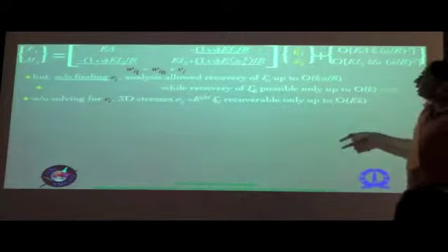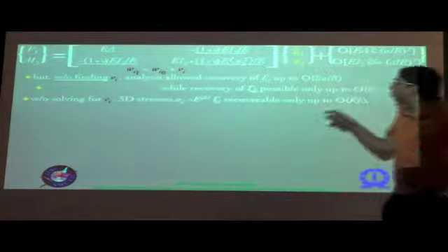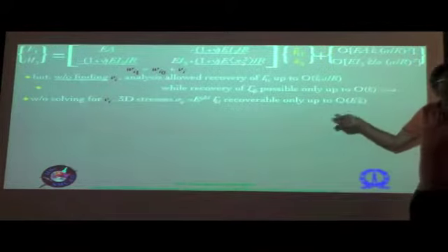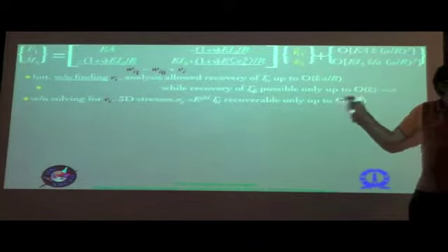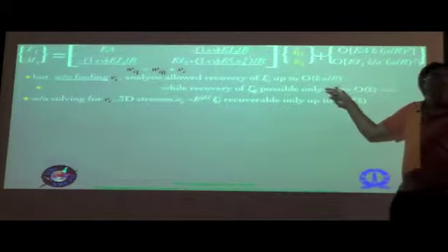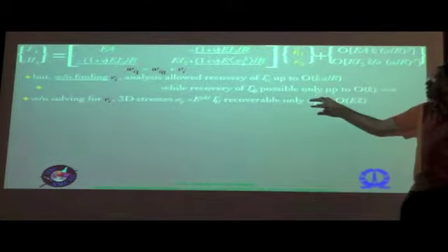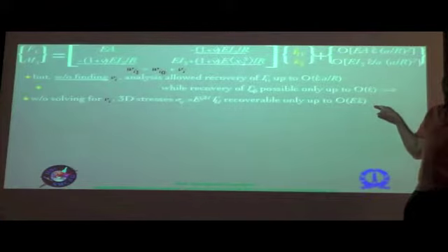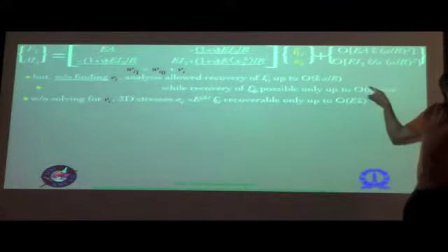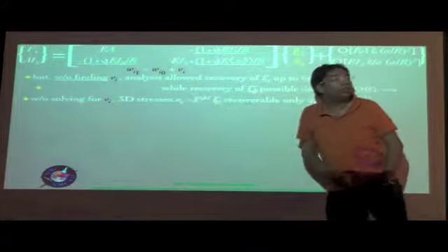Therefore, in the stresses also, you would have the recovery only up to E times epsilon hat. There would be some spurious terms coming because of this, but you cannot say that the stress is accurate up to the order E epsilon hat into A by R, because some of those were absent in being substituted here, and therefore in the recovery of the stresses.